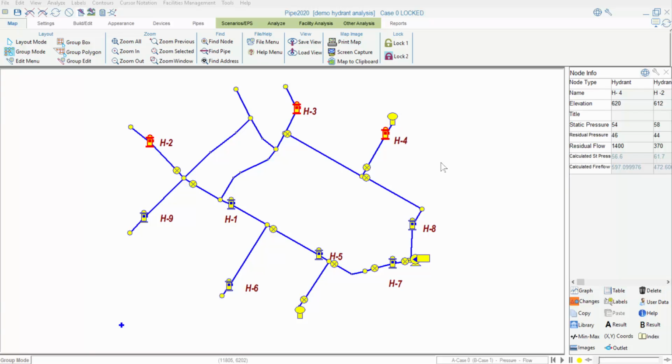And by results, I mean the fireflow at the specified minimum pressure, which is used for National Fire Protection Association hydrant color coding. However, one question that comes up is, are all 3 of these hydrants flowing simultaneously, or is the program analyzing each individually?